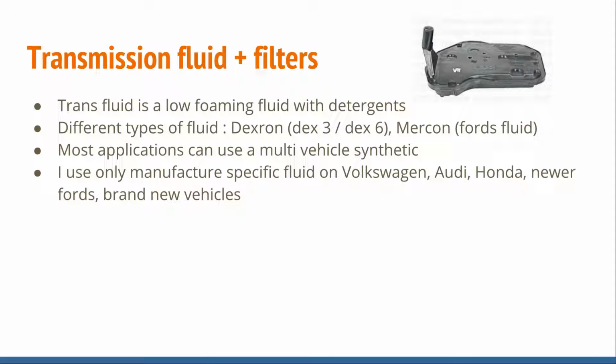But there are certain transmissions that we have to use specific fluid on, or factory fluid. Volkswagen, Audi. I use it on Hondas and also brand new vehicles. Newer Fords have a special transmission fluid that I don't believe is qualified yet in my universal or multi-vehicle fluid.